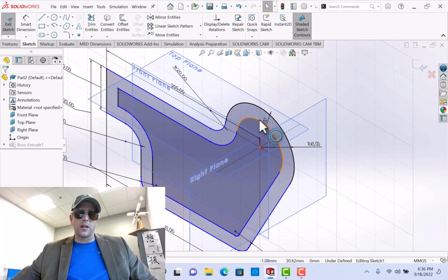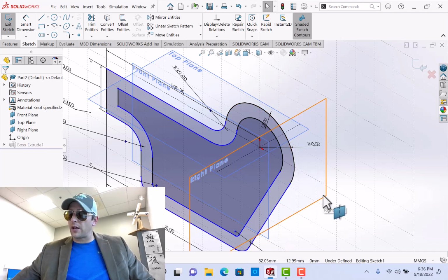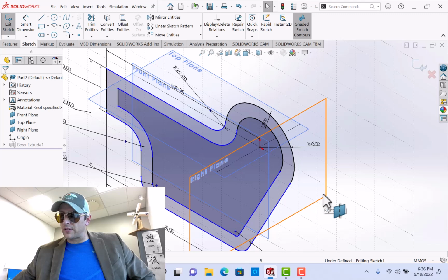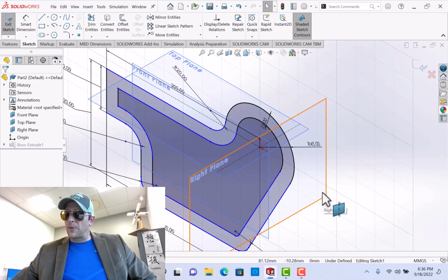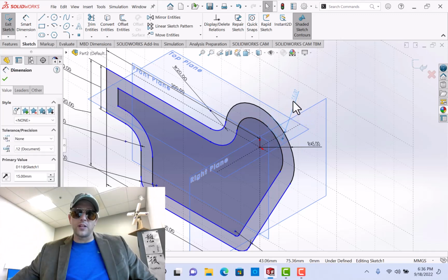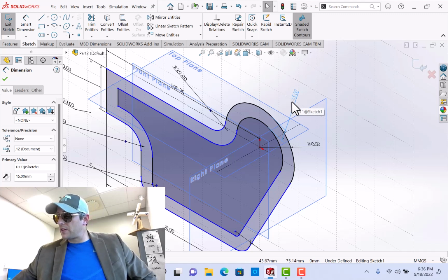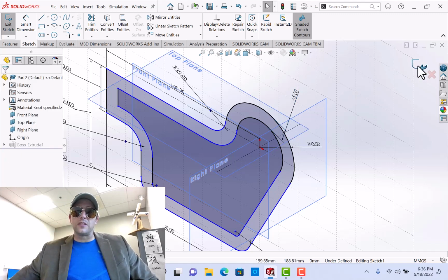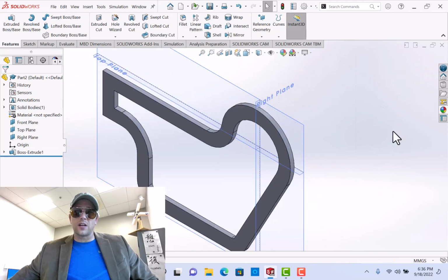So now that I've put the offset at 15, I had to click on the whole strand that we're seeing, the whole strand of the lines together. And I had to click on the relations of those lines to be able to do that. But basically, you could either lasso or do that somehow through those steps. So we then have this 5 and then 15. You're supposed to select 15 later, which is then offset. And so then the real easy step is to exit the sketch at this point and extrude